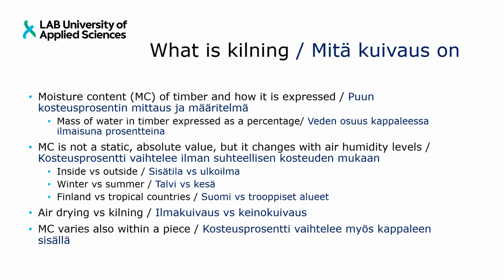It's also very important to remember in future life, in many practical instances, you will come across this one, that moisture content also varies within a piece. So, for instance, if you take the reading of the moisture content, you really can't use the surface measurement, and inside is quite different. So usually when you take the measurement, if you have the moisture meter, you put the prongs, the little needles, deeper into the piece.